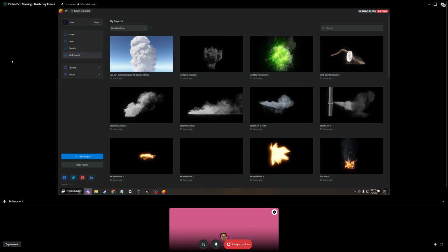If we go to our force and turn on our buoyancy, let's say we max it out to 250. You can see that now the smoke is actually getting sucked up because there's so much upward velocity. One cool thing that we added in 1.0 is you can enable gizmos to see what your forces are doing. And you'll be able to see why I'm saying that if you master forces, you can master your simulation.